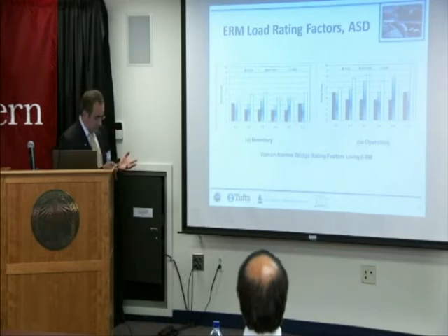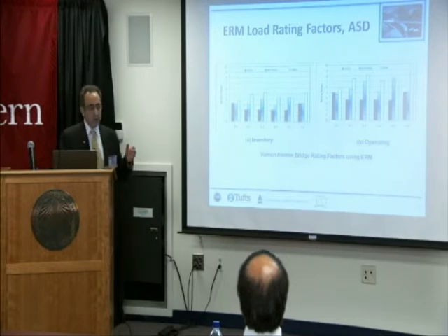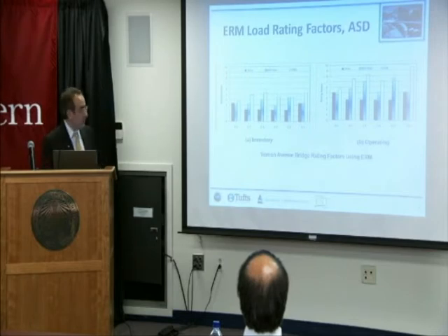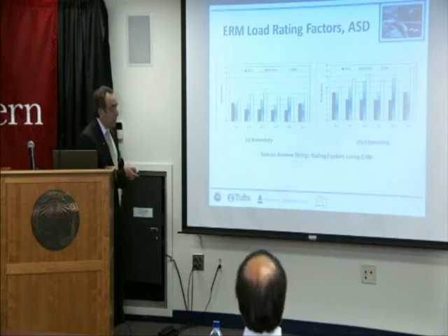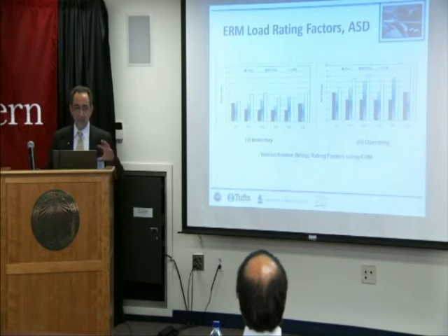Two things to mention here. You see that these girders 1 through 6 do not show symmetrical capacities, and this is due to the fact that there is a large sidewalk on the right side when you're facing north. So you get a higher capacity, especially when you model that. Also, overall, near the edges, you see similar capacities, but in the middle, you see that we have additional capacity in load rating.